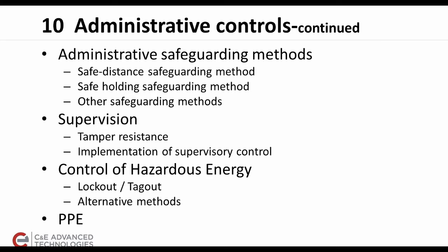There's a new section on supervision on tamper resistance, and what that talks about is not only how to make an adjustment tamper resistant, never talk about tamper proof because that's an impractical goal, but also on the implementation of tamper resistance, such as you don't keep the key in the lock, you don't write the secure password, HMI, what have you, those kinds of things.